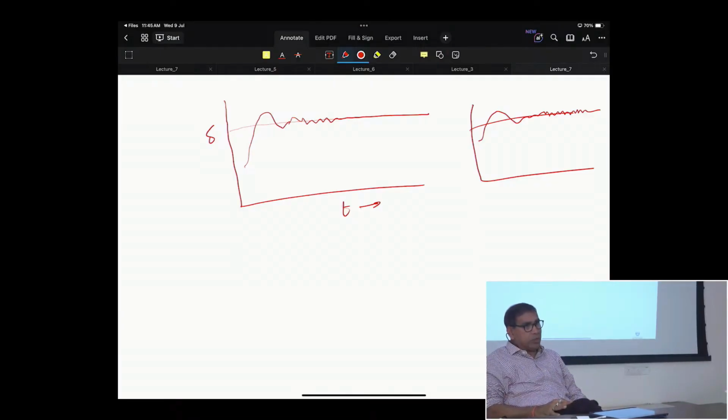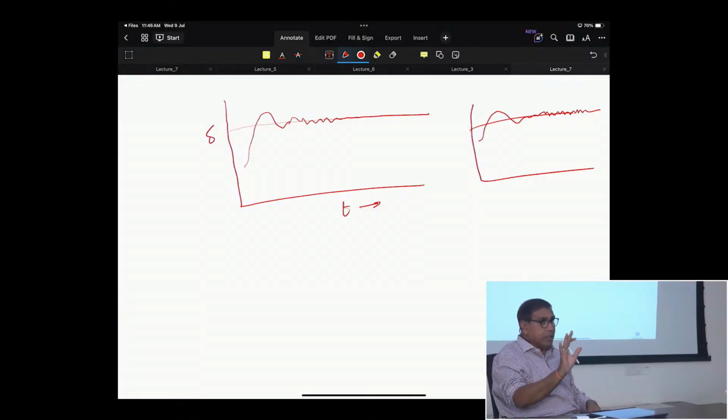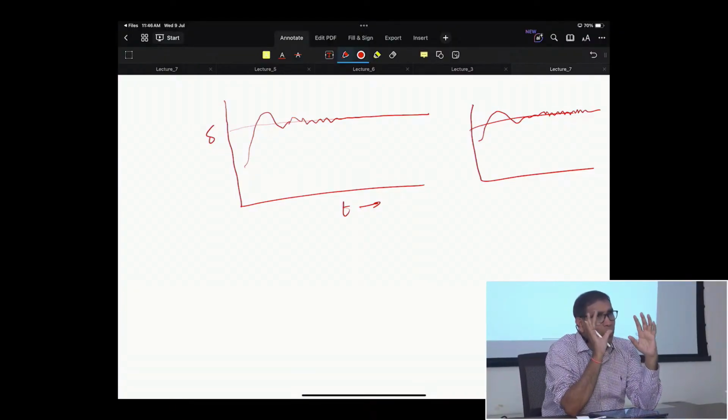You do not understand the control theory, then how did he get it? The student may not have included any noise, so therefore he got it. If there is no noise, then what is the point of minimum variance? If there is no noise, why are you implementing a minimum variance controller? As academics, you must be very careful in this case. If the problem formulation is faulty, there is no noise, and you are implementing a minimum variance controller, U is equal to minus G by BF, because it is there. You got my point? So minimum variance controller means the output will have some variance.